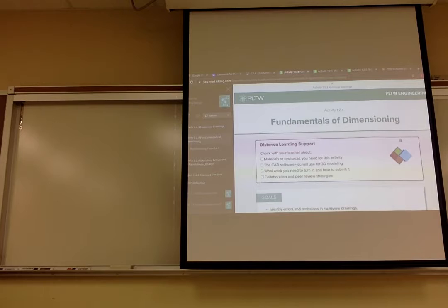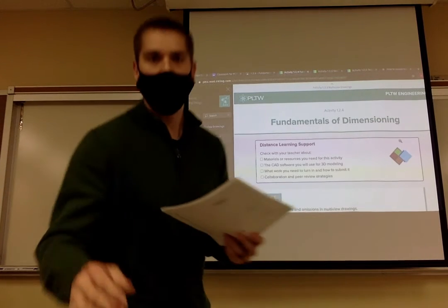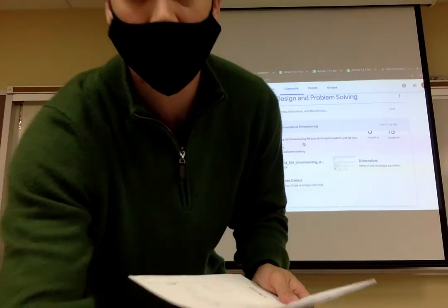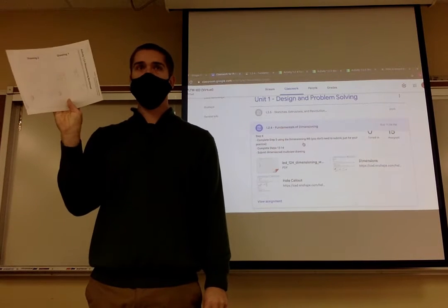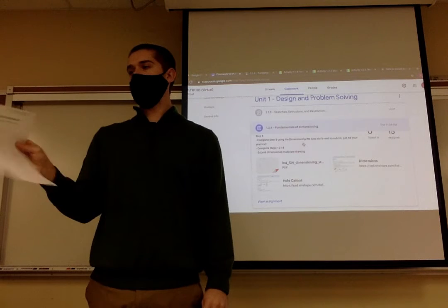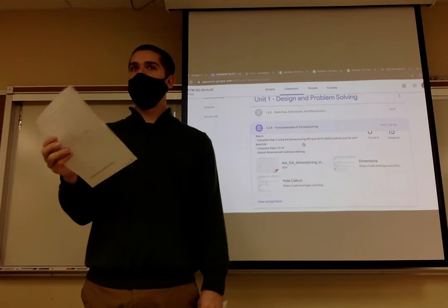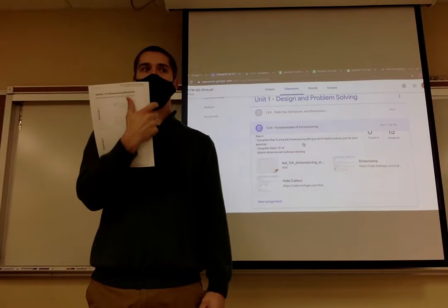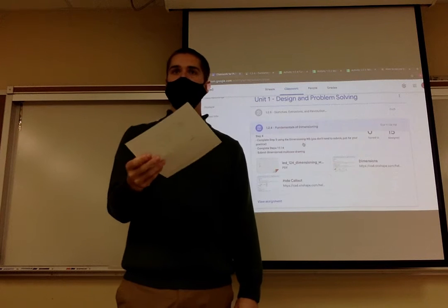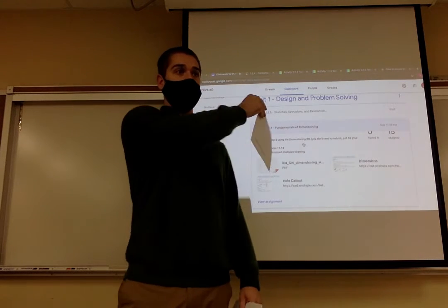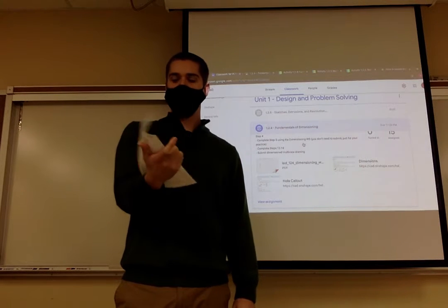So what I'm going to do, virtual students, this worksheet is linked on Google Classroom for this assignment. This is a practice worksheet for how to make dimensions. There's a couple simple parts. I want you guys to work through this. Feel free to work with your table partner, but start adding dimensions. Practice dimensioning a part, making sure you get everything, making sure you don't over-dimension, like do the same thing twice, drawing those leader lines, dimension lines correctly.